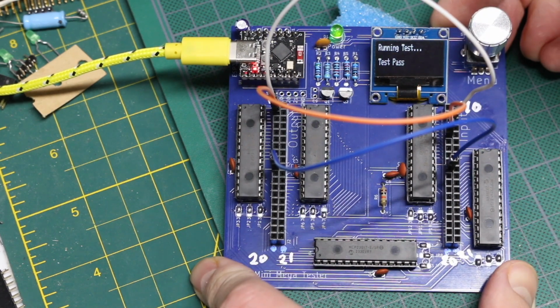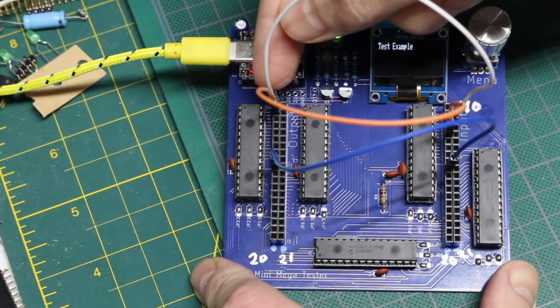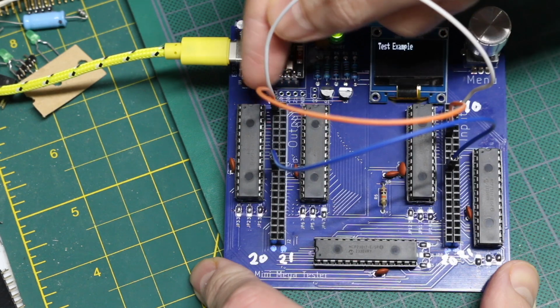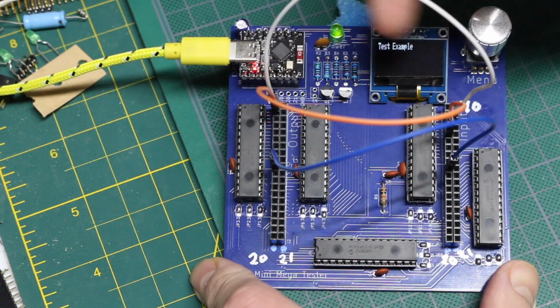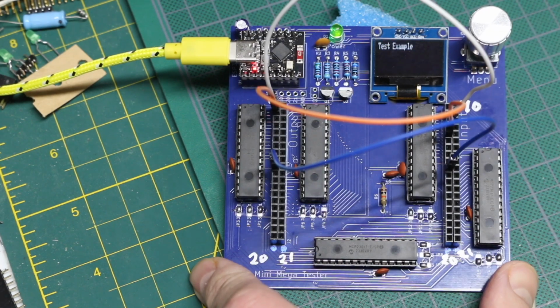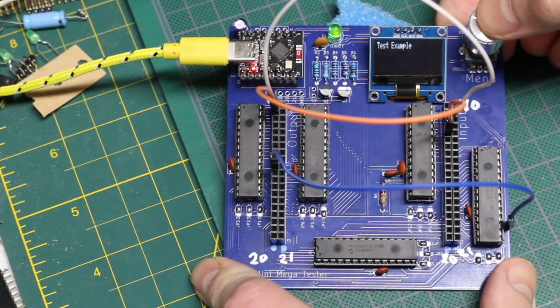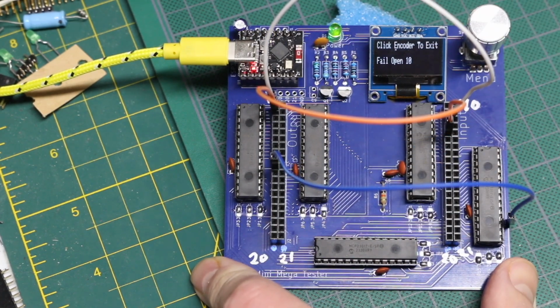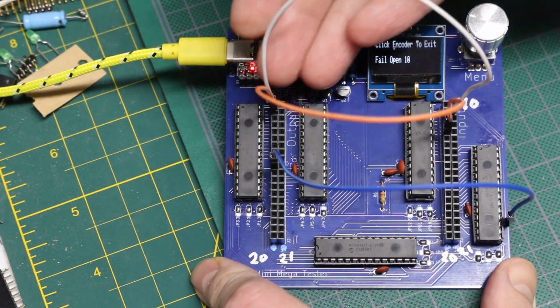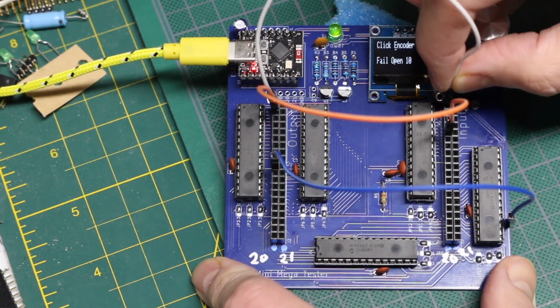it's going to pass. And I created the test to look for connections between output headers pin 1, 2, and 10 going to input headers pin 3, 5, and 10, just to show some examples. So if I unplug the cable on pin 10 and run the test, it will detect an open failure on pin 10. And if I take the output pin 1 cable and put it somewhere it's not supposed to go,